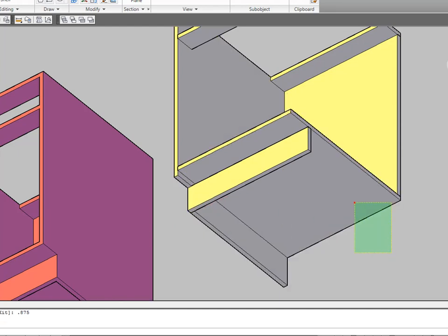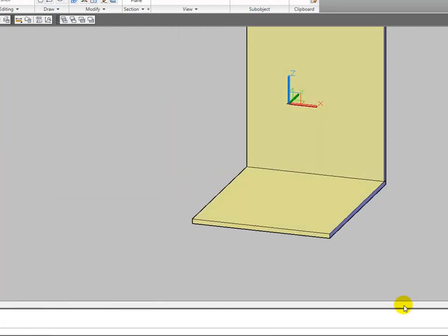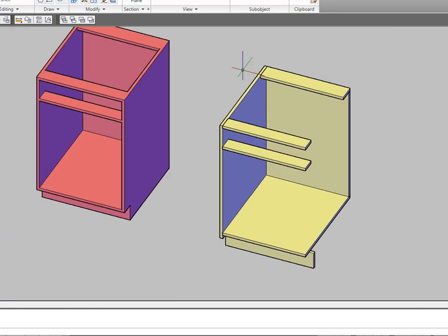I also decided that I want to change the width of this cabinet. Decided I want to make it bigger. I want to end up with a 30-inch wide face frame. And what that means is that I also want 1/4 inch scribe on either side of the box. So that means that my box itself is going to have to be 29.5 inch wide to create that scribe, and half of that is 14 3/4.